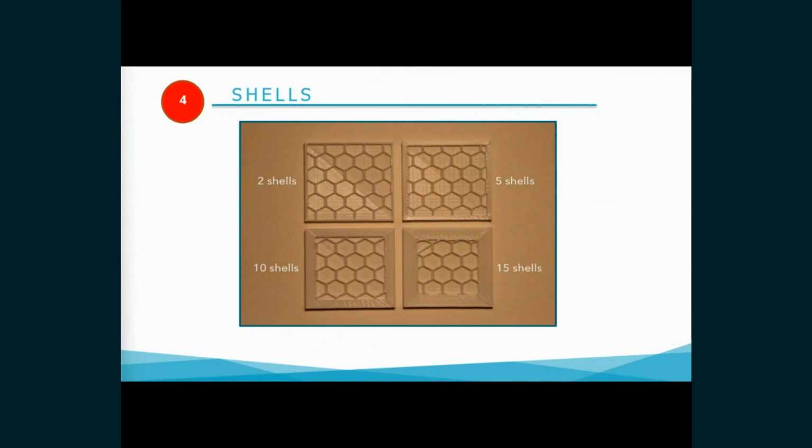The relationship between shells and infill is interconnected. Shells determine the outer appearance and define the overall shape. The infill provides internal structure and affects the structural integrity of the object. Finding the right balance between shell thickness and infill density is essential for achieving the desired strength, weight, and print time for the given object.